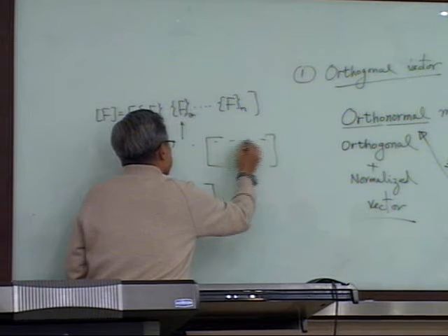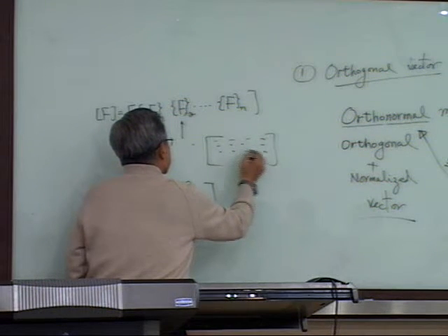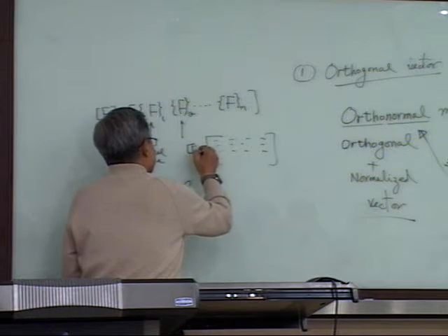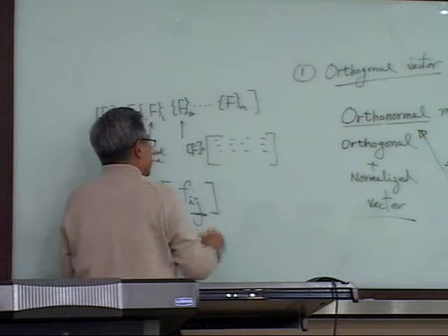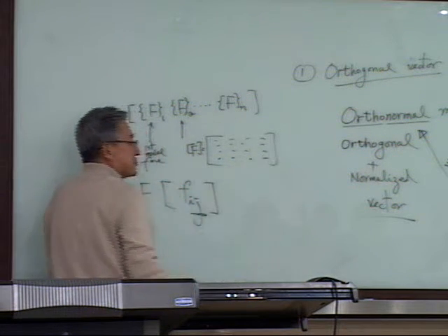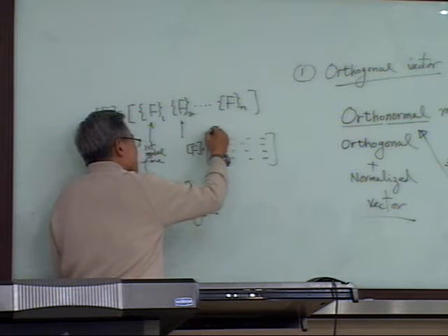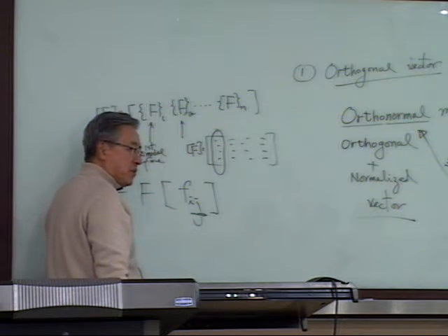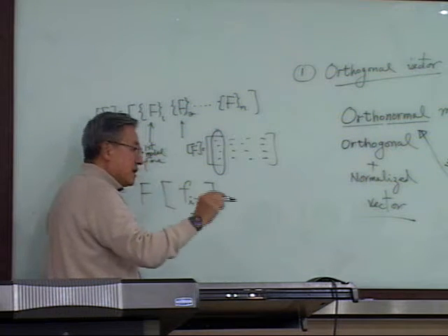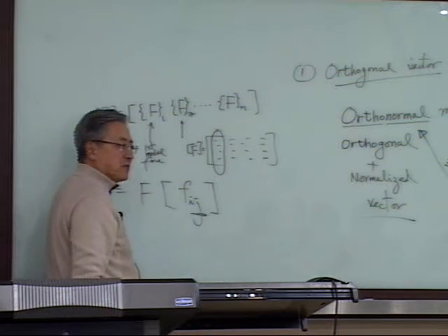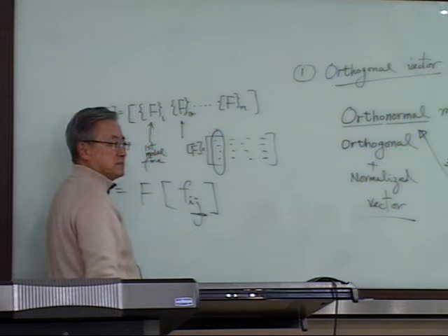I need a complete entry of this forcing function. I call it F i j. This is what entry you need. And each entry is a force in every mode. Then you apply it as a static force to the system.